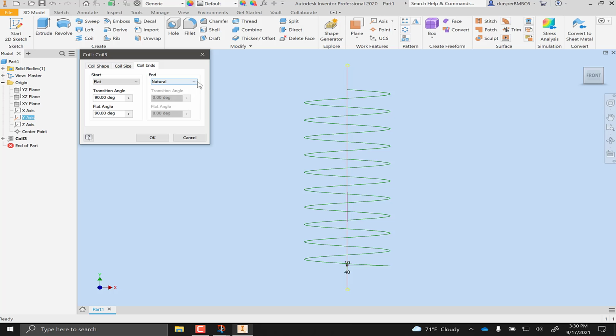If you have a car spring and it ends like that, that could cut into the part that it rides on. But if it is flat like down here, then all of this makes contact with the metal that the metal container has to sit in. And so it tends to wear it a lot longer, or does not wear it out as quickly as this will. This will chop a hole in it eventually, whereas this will take years. So that's what the advantage is.